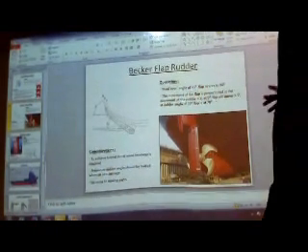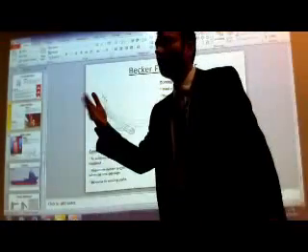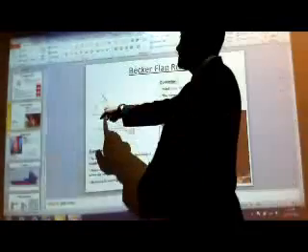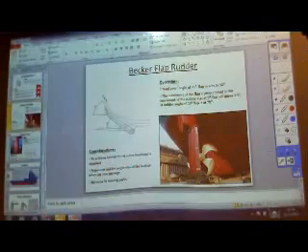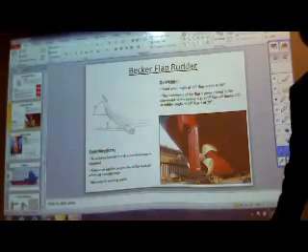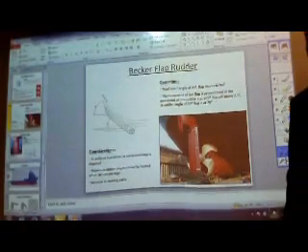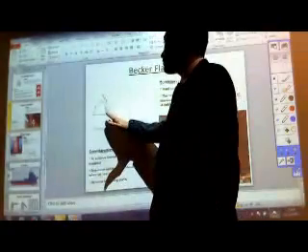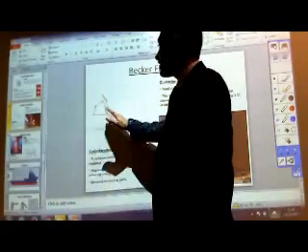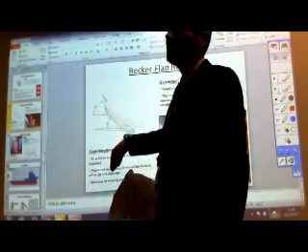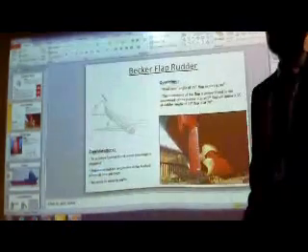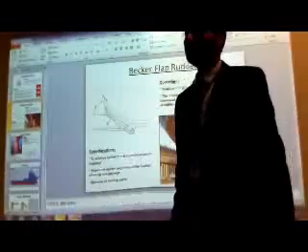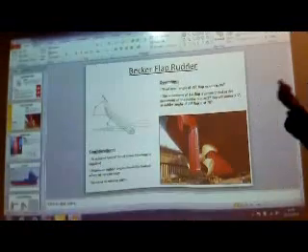This is a Becker rudder. It is like a fin, like a tail of a fish. Can you see this? Another bit here. What is this going to do? Create higher lifts, increase the lift of the ship. Because this bigger portion of the rudder can only go to a certain angle; the area of operation of a conventional rudder is about 30 to 40 degrees on either side. What this does is add another tail to it, and then it can increase the lift. That is one of the designs.